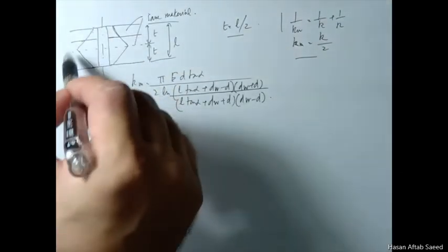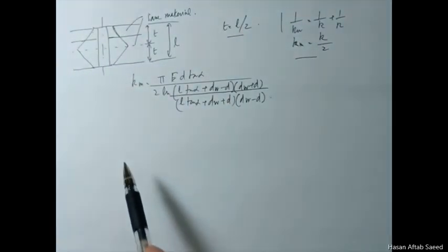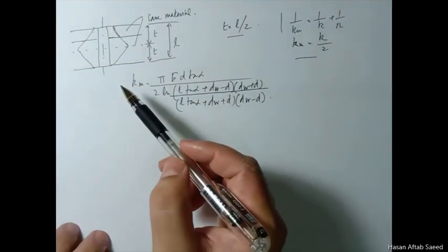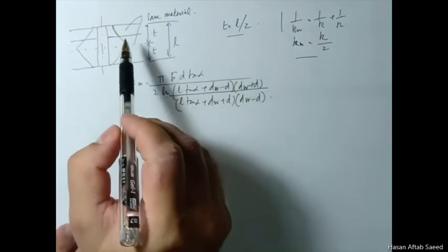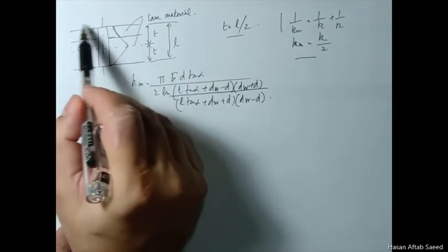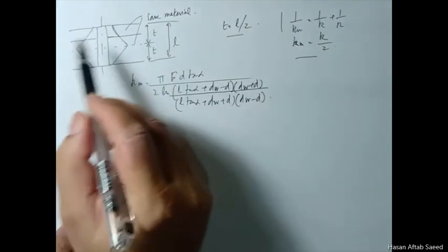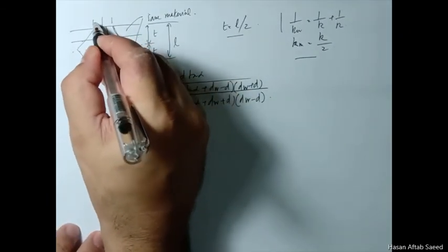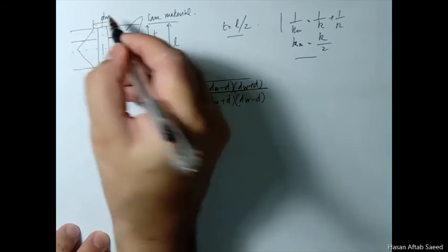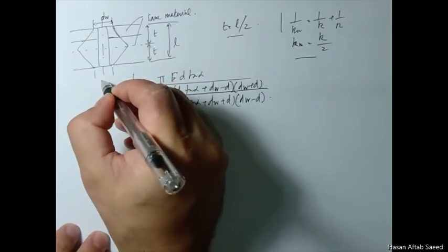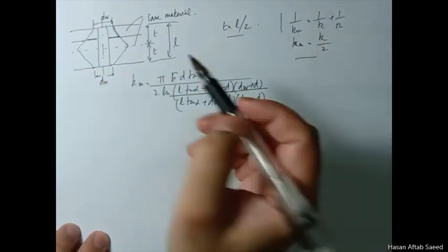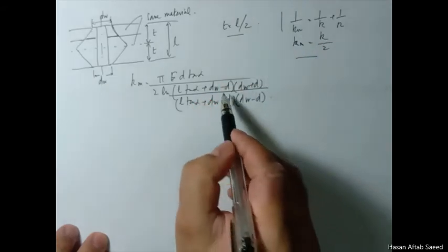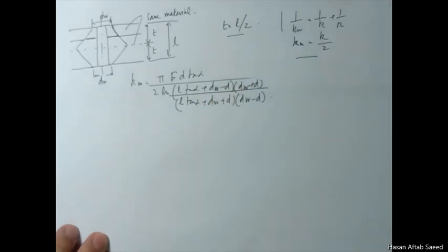But when you have this special case where you have the same material, it doesn't matter what the thickness of these members is. What matters is that you have two identical frustra. One starts from here, formerly D, now you call washer diameter. The second one, dW. There's a D here also, but you don't separate this and this, so we dispense with the big D and just use dW.